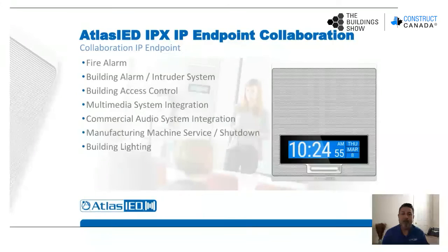So by using the handshaking capabilities, the connections in the IP endpoint devices, the IP endpoints can actually mute those local systems. So the only audio source in that space is actually coming from the IP speaker during the message. Now, after the message, the devices will actually unmute the local audio system, so those systems can go back and resume their normal operation in sessions for that particular space.